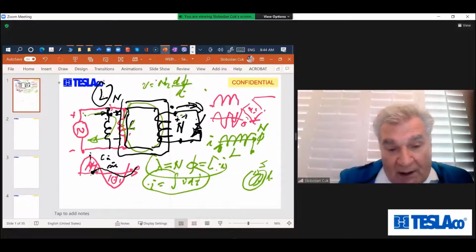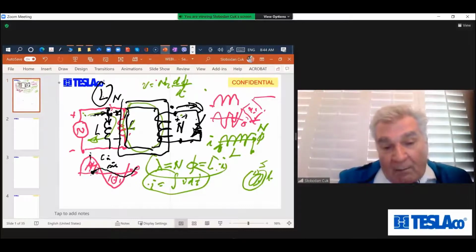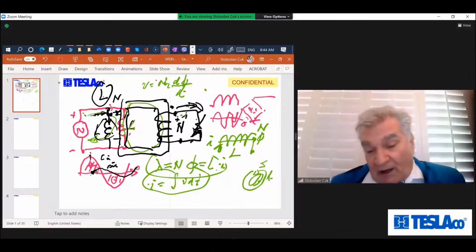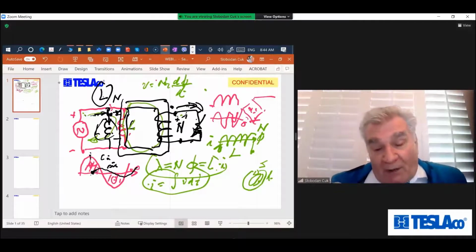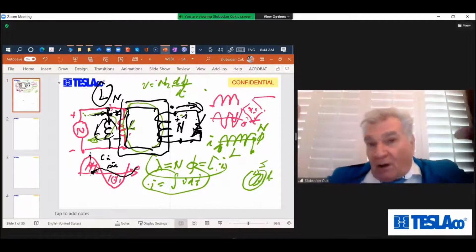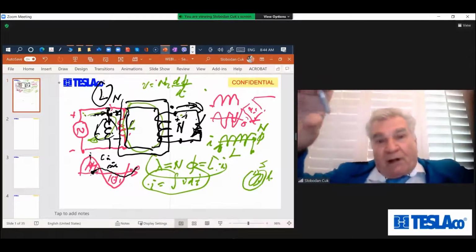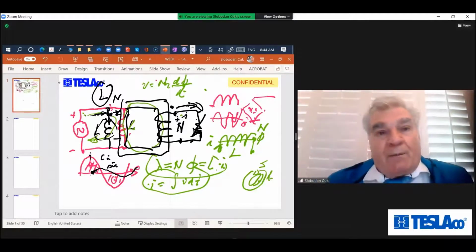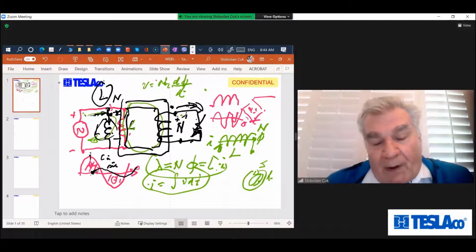So what is the current in this magnetizing inductance? It is the difference between the input current minus the reflected output current, which is the same small magnetizing current due to that AC inductor. You get it? That is important. That's most important. That's the transformer we need to build in the switching converters, and not the transformer with the concoction of the full bridge primary side and 4-diode secondary side. It doesn't satisfy the requirements that the transformer needs: volt-second balance or flux balance and charge balance, okay?